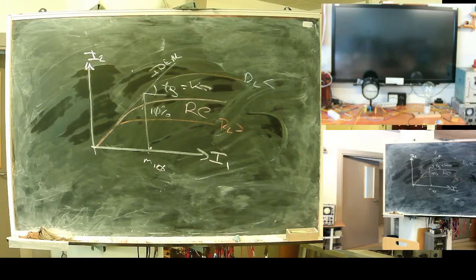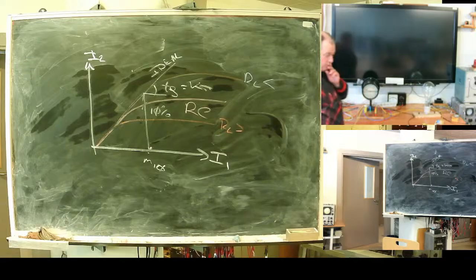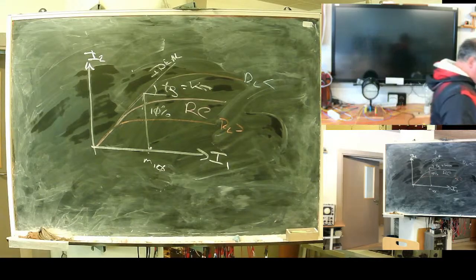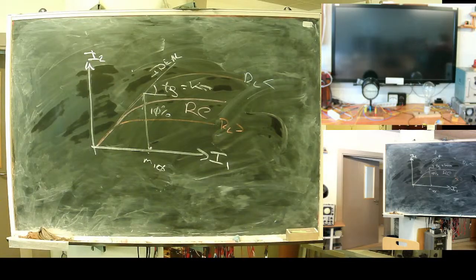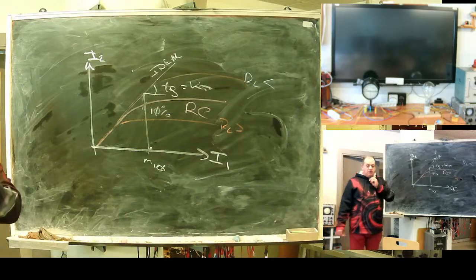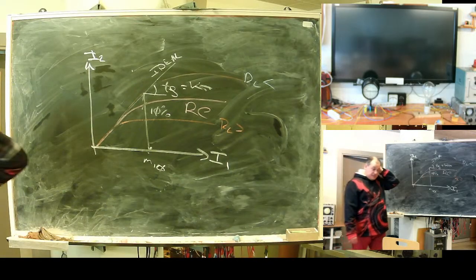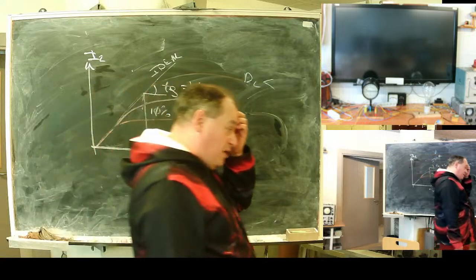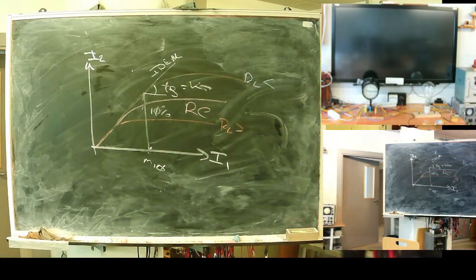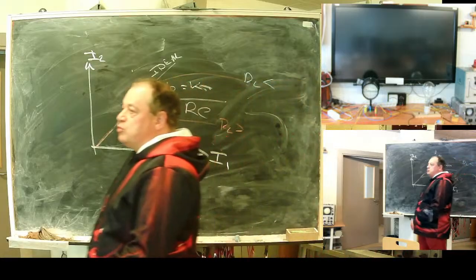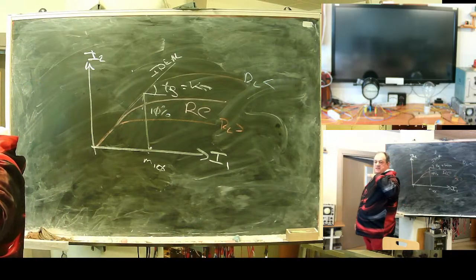Something very testable will push you out from the low voltages, and it's noise from your own power supply. It sounds ridiculous, but if you try to operate on a very low voltage level at the input of the ADC, you will see terrible things. Noise from your own power supply will disturb your signal.